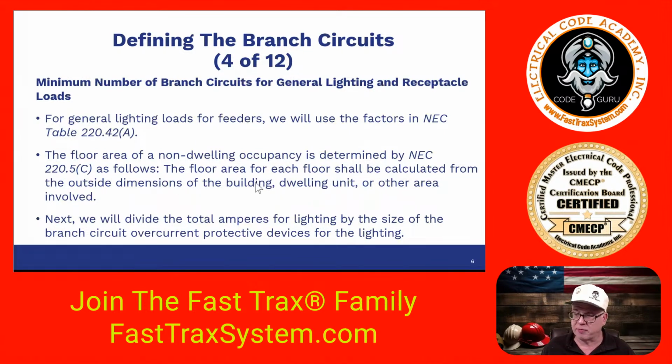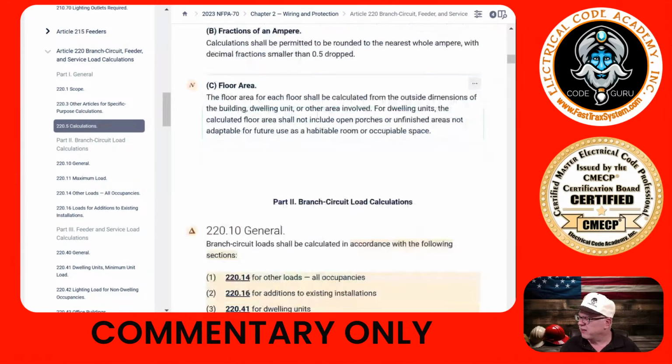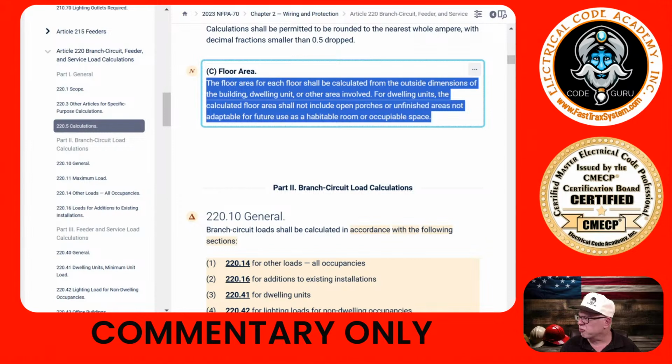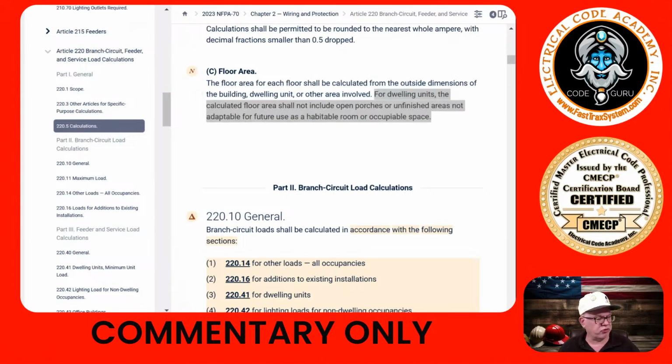Going to 220.5 for context, this little note means it's new, relocated for the 2023 edition. We ignore the dwelling unit part. It's the general rule that when finding the square footage of a building, even in commercial, it is the outside dimensions of the building itself.